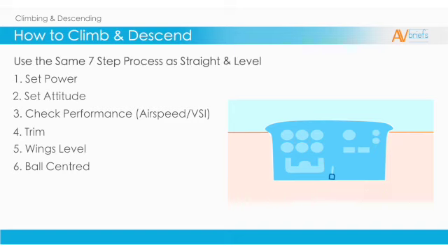Check the balance ball is centered. This is to make sure you are holding in enough right rudder. Usually if you're not holding enough rudder, the heading will slowly drift off your intended heading. So that's a good check.